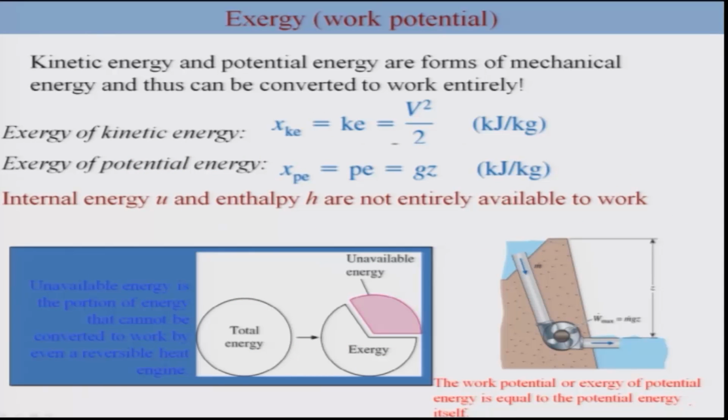So, let us continue and ask the question: what about the exergy of kinetic energy or potential energy, which are forms of mechanical energy? As we know from our past exercises, kinetic energy and potential energy can be converted to work entirely, and thus the exergy of kinetic energy is simply the kinetic energy, and the exergy of potential energy is simply the potential energy. However, this is not true if we consider internal energy and enthalpy, which are macroscopic, molecular level microscopic energies, and they are not entirely available to work. So, internal energy and enthalpy are not entirely available to work.